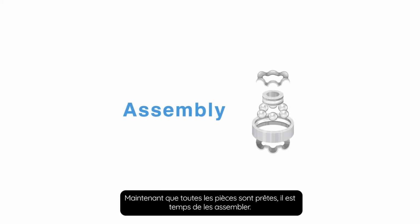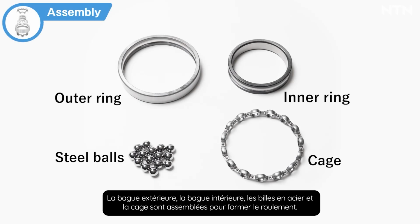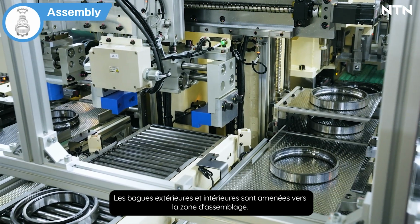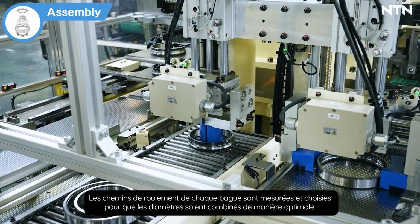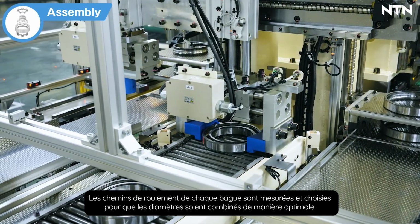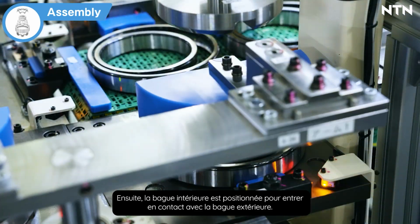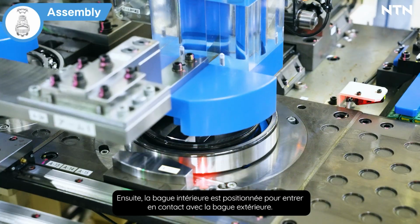Now that all the parts are ready, it's time to assemble them. The outer ring, inner ring, steel balls, and cage are assembled to form the bearing. The outer and inner rings are brought to the assembly area. The raceways of each ring are matched so that their diameters are optimally combined. Next, the inner ring is positioned so that it contacts the outer ring.